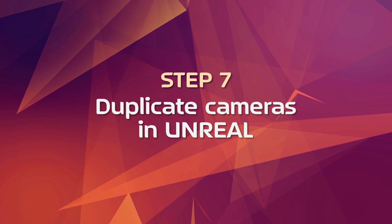Unreal will have offset the new camera's location by 10 centimeters even though you didn't ask it to. So to fix this, in the Details panel, click to reset its location. Click to make sure UECam02 is selected in the outliner. Press Ctrl D to duplicate it. Press F2 and adjust the naming to be UECam03.